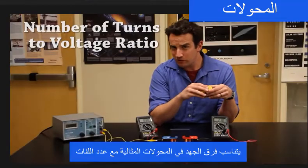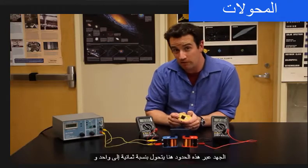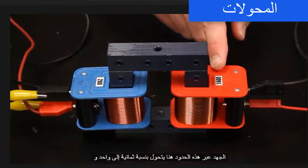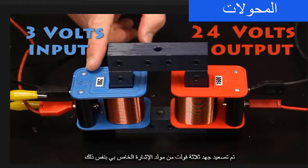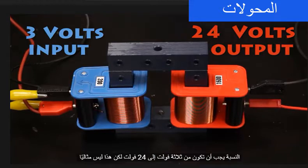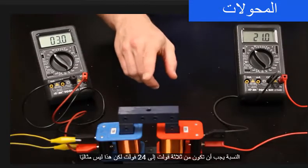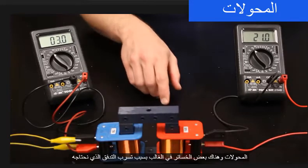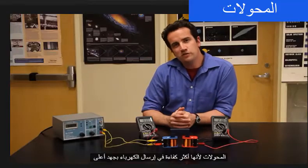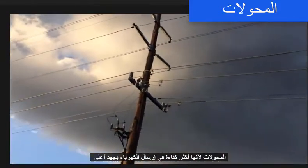The number of turns on an ideal transformer is in proportion to the voltage across those turns. Here I have turns in an 8:1 ratio, and the voltage of 3 volts from my signal generator is stepped up by that same ratio. It should be 3 volts to 24 volts, but this is not an ideal transformer, and there are some losses, mostly due to flux leakage. We need transformers because it's more efficient to send electricity at higher voltages.